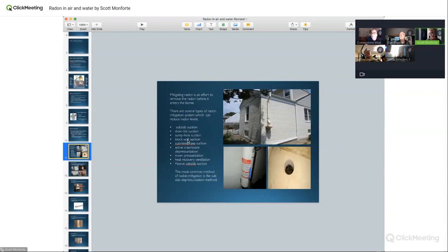And we'll talk about the different types of fans that we use. There's basically a couple fans that we use all the time. We have a high suction fan for tight soil, and a medium air velocity for gravel and all that. And then you can go high suction in schools, big footprints. You can go high CFM. We're kind of in the middle with the two of those. And then you can go up and down.